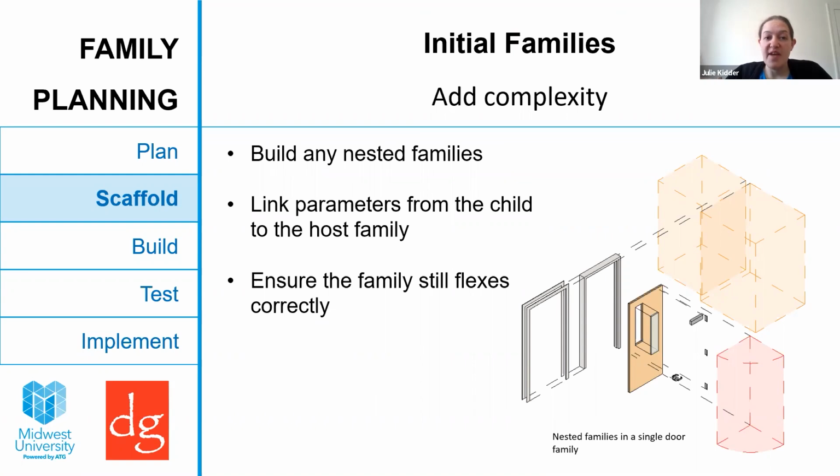Do I have a single master shared parameter for all projects in the office? We have one that is for everything that goes in the template. And if projects have specific shared parameters that are unique to their project, they get a supplementary one. And then anything that is valid will get worked back in. But all of my door parameters are in the single master shared parameter file that we have.